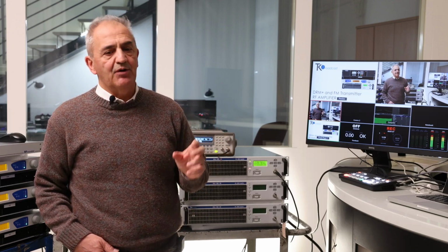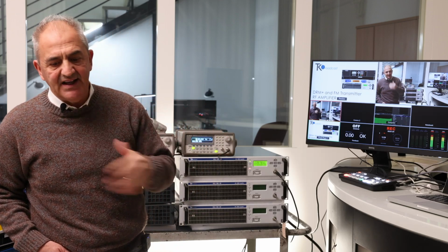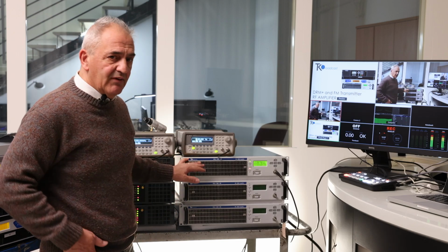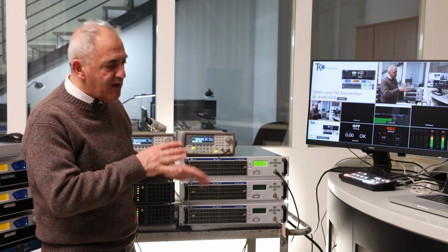Moreover, it has multiple carriers. What is the point? Sometimes it can happen that each carrier has the maximum value, or one of the maximum values, at the same time. They are added together and can create very high peaks of power. So the ratio between the maximum power and the average power here on the iBiquity is very high. For this reason, we are using a 1.2 kilowatt amplifier to get around 300 watts iBiquity.